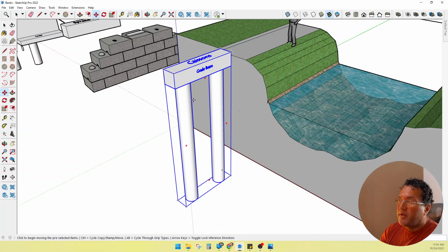Okay, and you're hoping that you don't slough off. When these rebar cages go down, if they start scraping the sides of the wall as they go down, it just creates a mess. If that happens, you have to pull the cages out, get the dirt back out, get the water back out, put the cages back in, wait for an inspector, city and county inspector, to go out there and inspect it. If he approves it, then you have to get concrete inside there. You just can't pour concrete inside it from the top. You have to pump it in.